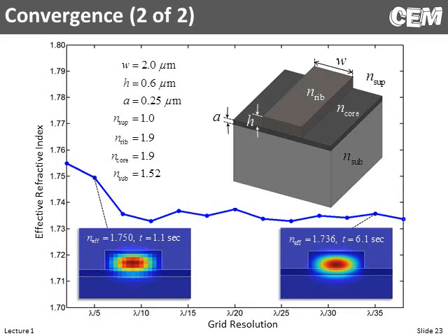In fact, the off-the-shelf software builds this in. It usually models things several times. It models it once, looks at where the fields are varying most abruptly, then goes and uses a denser mesh around those points. And it just keeps going and adding more points, automatically built in. So the codes in this class aren't going to be that sophisticated. You're going to run it, add more points, and run it again until your answer doesn't change a whole lot. But that's going to be standard practice for you. Always looking for convergence.